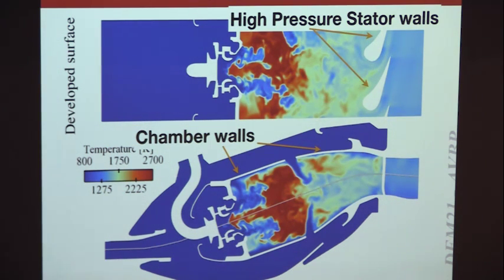Now you all probably have done this experiment, you know, if you take a lighter and you can have your finger above the flame, and you know that if you go fast enough, it's okay. If you stay, it's not okay. So you see, by the way, that flame-wall interaction is going to involve quite a few phenomena which are difficult to draw in 2 seconds. One of the first things is, if you put any surface in a flame, the surface will receive a high heat flux. That's how you get burned.